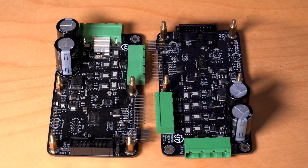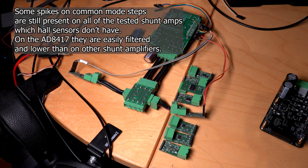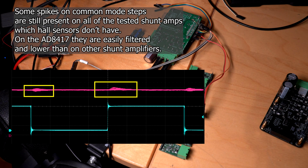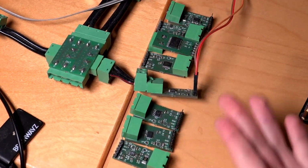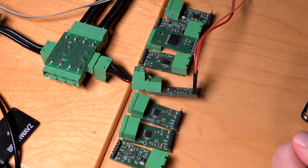And this one provides pretty much excellent PWM rejection for a shunt amplifier, but it still is a very sensitive part that can be easily damaged during assembly or when misused from overvoltage, for example. In search for a better alternative with possibly even better noise rejection, I modified an old driver and made some breakout boards for different sensors to connect externally.